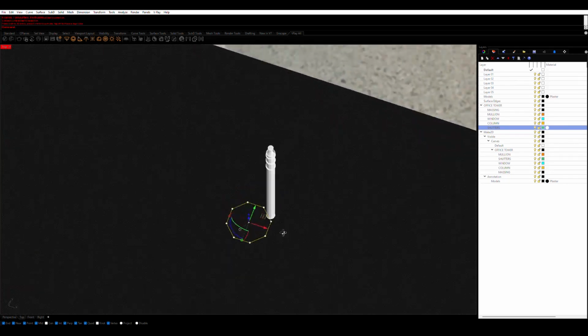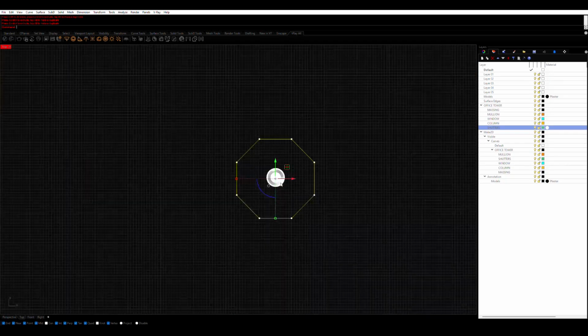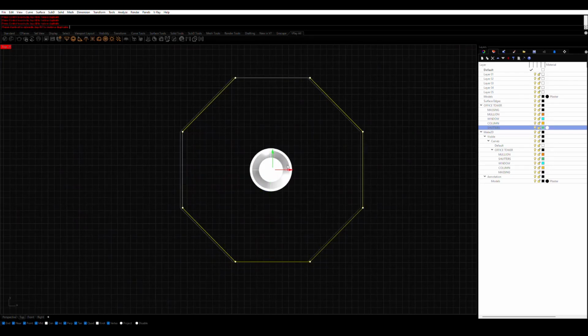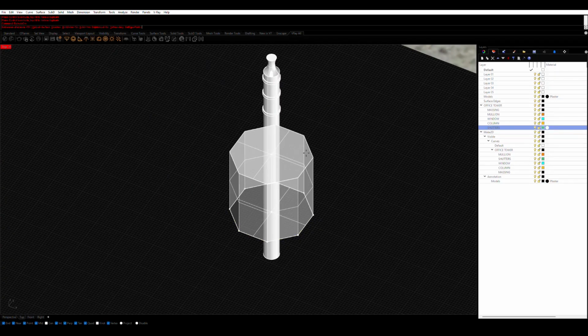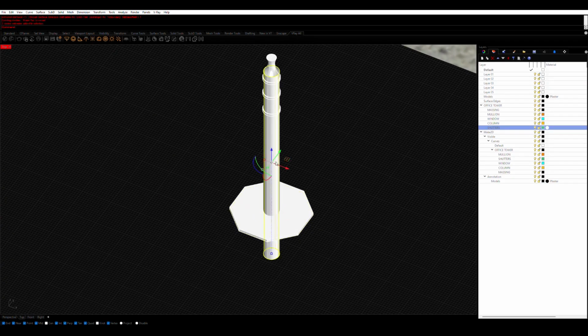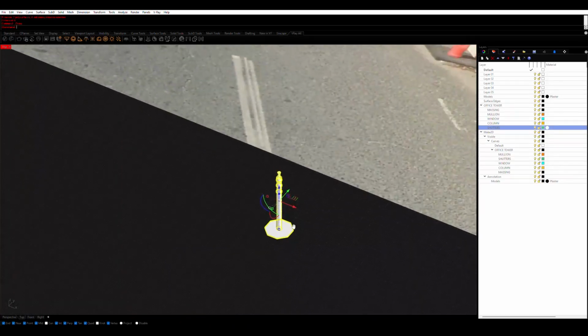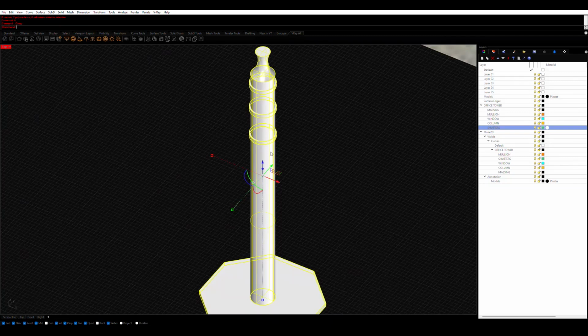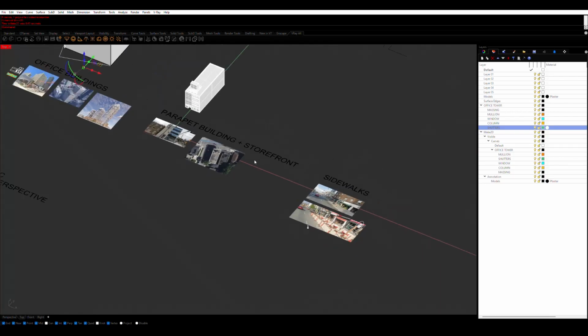And let's say we get the base in place. You can align this, snap it in place. I'm just going to align it very roughly. And let's just raise this by 1 inch. Remove the bottom portion, difference it out. And let's just say we group this together. You don't even need to join it. Or actually, probably better to Boolean union. And let's see how this looks.